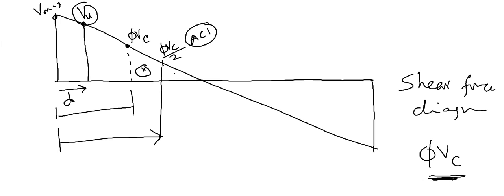Any area with shear force less than this, no reinforcement required at all. Even your code did not say provide reinforcement here. You can provide some reinforcement here just to tie the bar, but you do not need it. In fact, you do not need it in this region also. You only need reinforcement here, but here we will provide just to satisfy the ACI requirement.